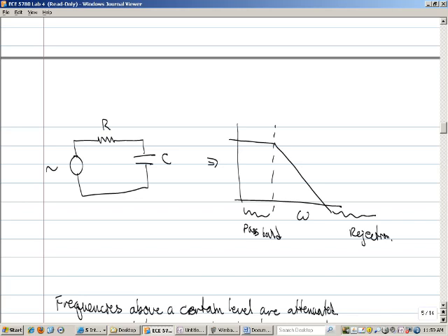What we're going to do next is consider a low-pass filter. I thought this was a software class. Why are you showing me a resistor? Sorry. Okay, so we've got an AC input going into a resistor. That goes into a capacitor. We're going to take the output in between the resistor and the capacitor. I assert that this is a low-pass filter. I hope you all already understand this. This is something you should have had in the beginning circuits class.